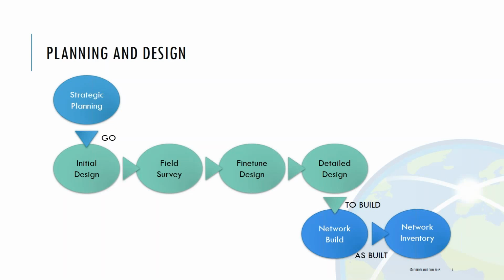From such a field survey, you typically will have some redlining information where you want to indicate which parts of the design would actually need to be changed because the situation in reality in the field is different from what was captured in the initial input data. Now, this fine-tuning step as such will then allow you to shift around some points or clusters or take different decisions, impose those on the design and re-optimize all the rest so you still have an optimized network within the given constraints. This can also be an iterative process, but once the planner is happy with his design, he can